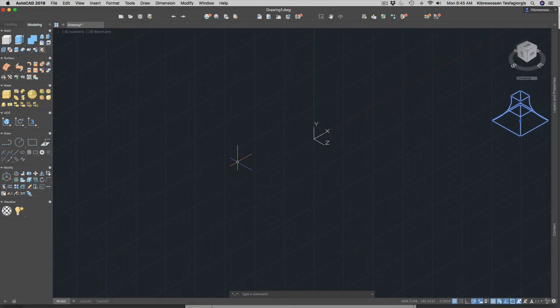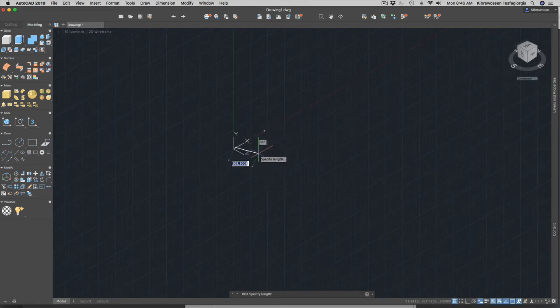Okay, so the second one starts, it says first switch to southeast isometric. So we are already on southeast isometric. I think my coordinate has rotated. I need to have x here, y there, and z there. That's the proper way of our UCS.